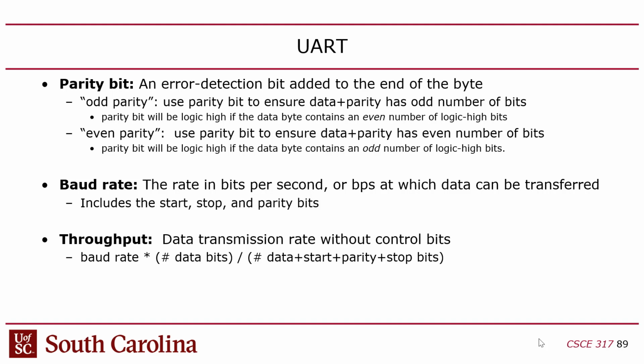Okay? Now the parity is an error detection mechanism that's added to allow the receiving side of the channel to know if there was an error. And so the idea is that you can choose between odd parity and even parity. In the case of odd parity, and this part is a little counterintuitive, I think. Some of you might have heard of parity, right? Parity is essentially determines whether you have an even or an odd number of 1 bits that are sent, right?